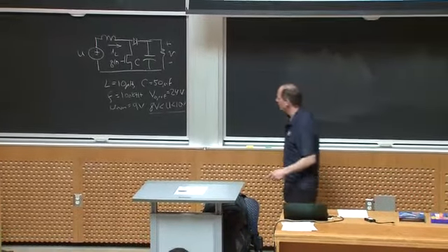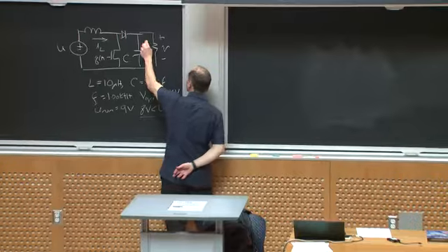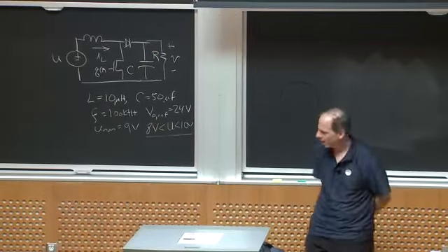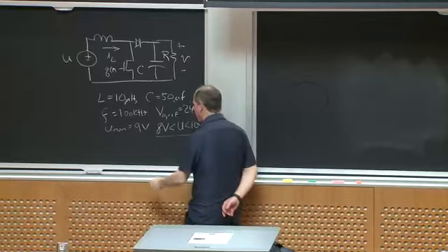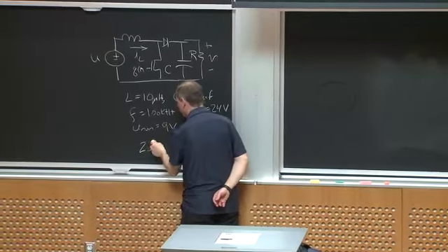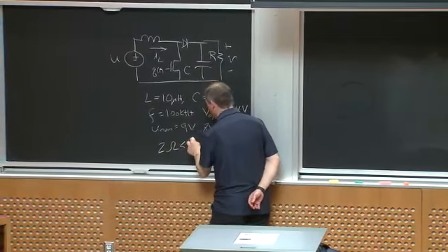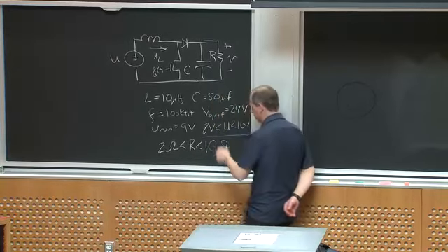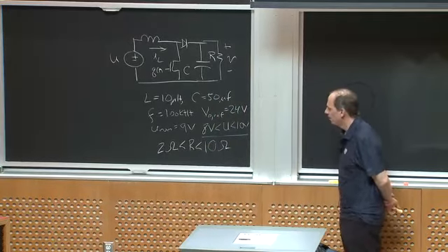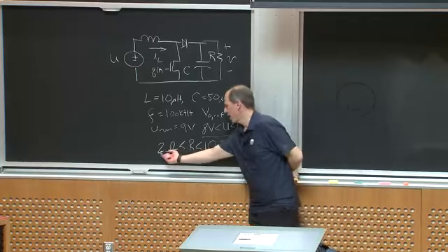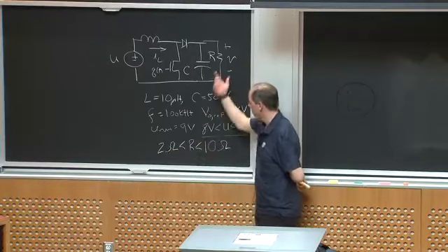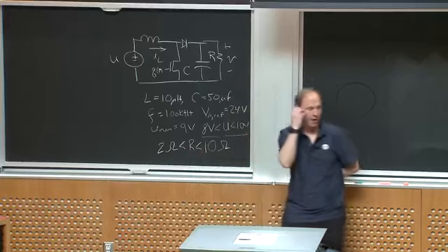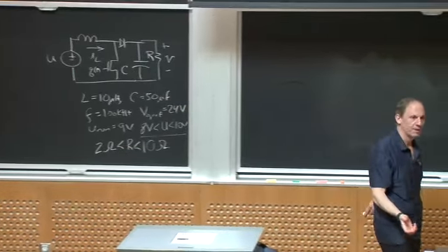The other thing we said we had to deal with was variations in the load resistor, okay? And I'm going to use a range of 2 ohms, that's the heaviest load, less than R less than 10 ohms. And I'm just going to use a pure resistive load for simplicity, okay? So this is the heavy load case. That's high power for a given output voltage. This is the low power case. This is about a 5 to 1 power range. All right, that's a little bit more respectable.